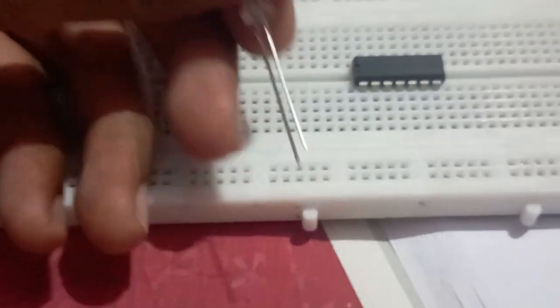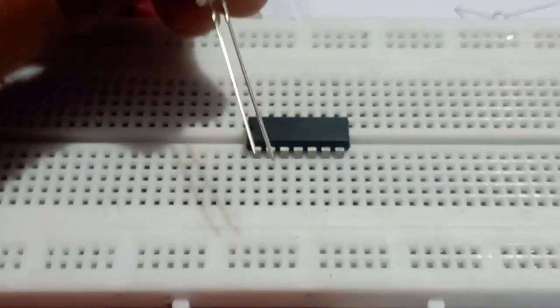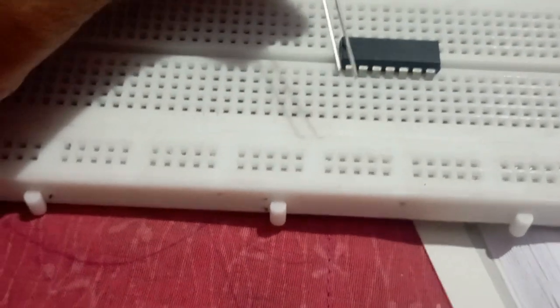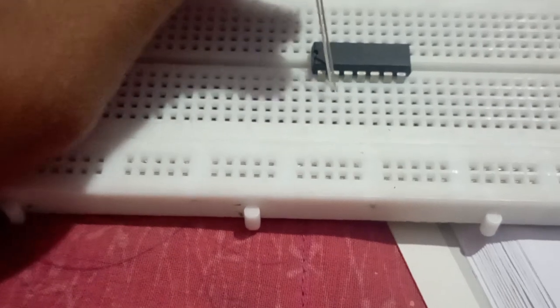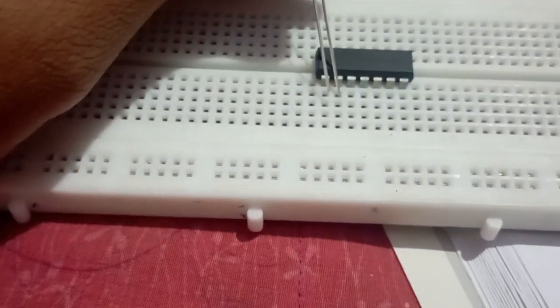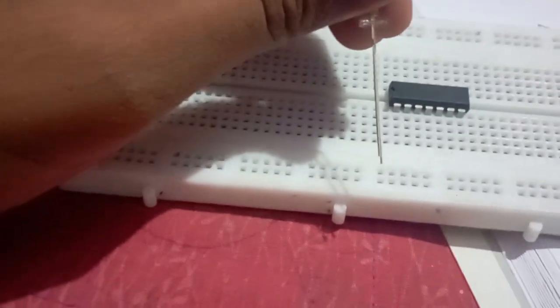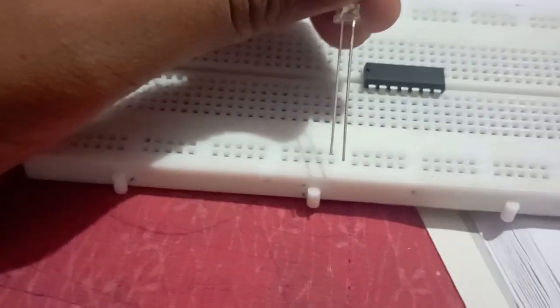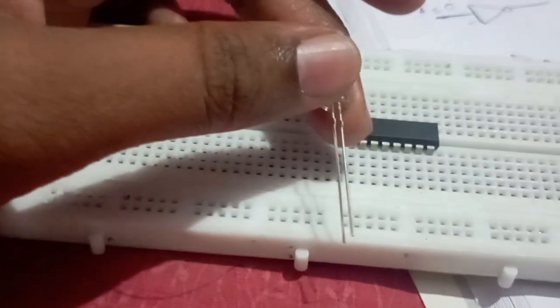So I am going to use this LED on the output side of the IC. How are we going to connect this LED? The positive is connected to the output, that is, the second pin of this IC, and the negative is grounded, that is, given to the negative of the battery. I am having a 9-volt battery, so I am going to connect a resistor in series with this LED, so that the LED must not burst. I am going to show the connection, how it is done, now.